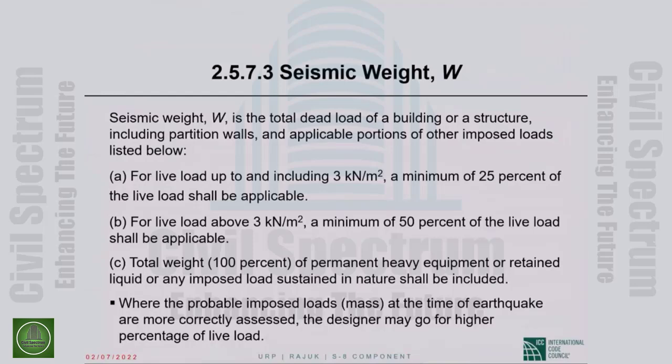Seismic weight of BNBC. Seismic weight is the total dead load of a building, of a structure, including partition walls and applicable portions of other imposed loads listed below. So very similar to ASCE 7, except dead load, it says including partition loads. And I believe those are fixed partitions that are being talked about. So applicable portions of other imposed loads, those are for live load. This is all different from ASCE 7.